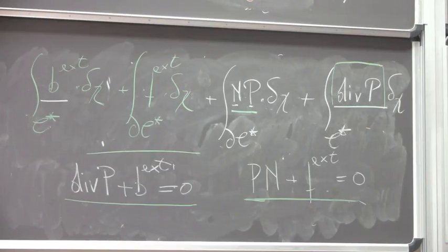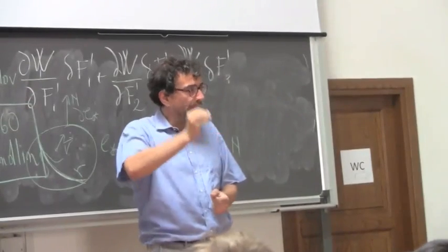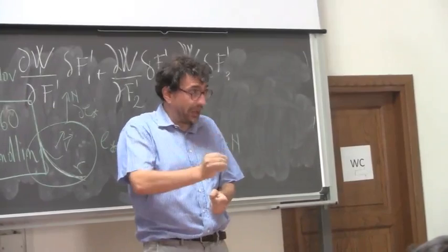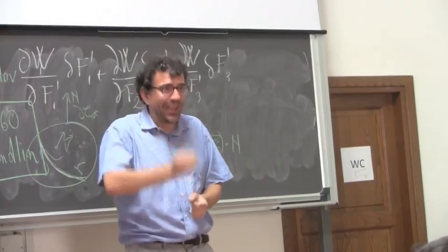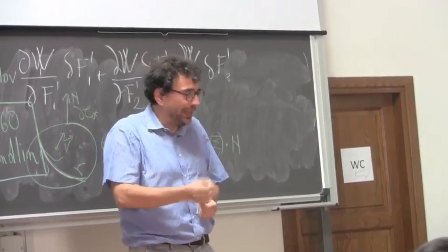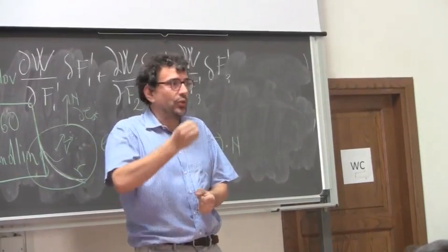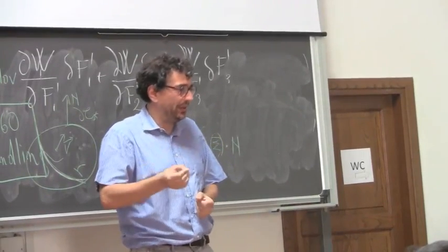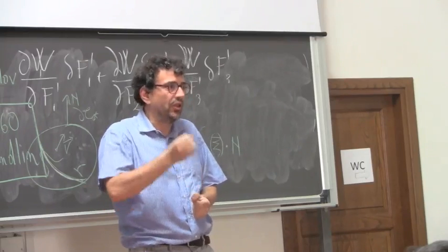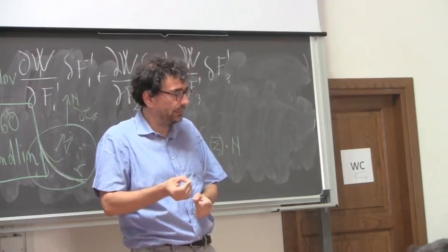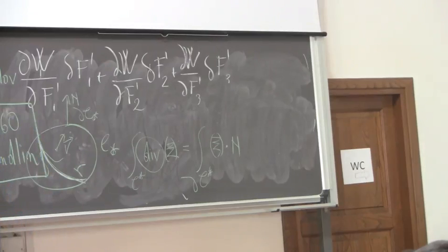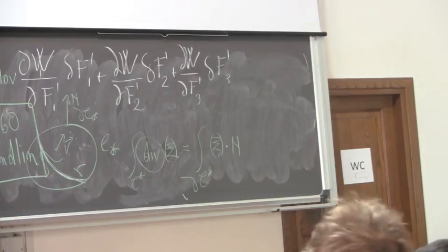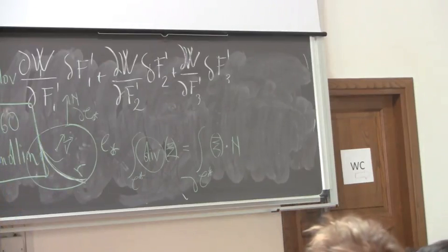If you have energies per unit volume, and these energies depend only on F, you cannot expect the capability of your continuum to sustain forces per unit line, or forces concentrated on one point. So if you have forces per unit line, or forces concentrated in one point, you must change your theory.